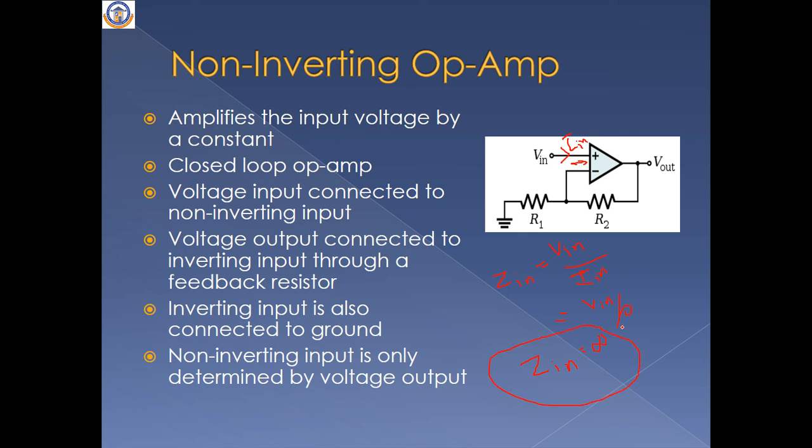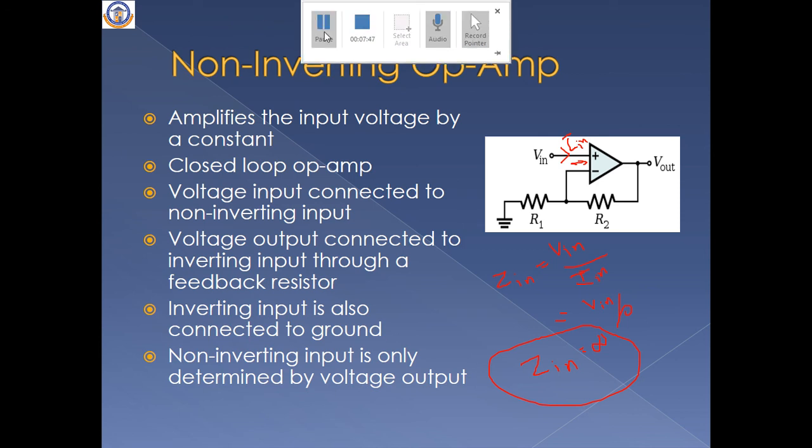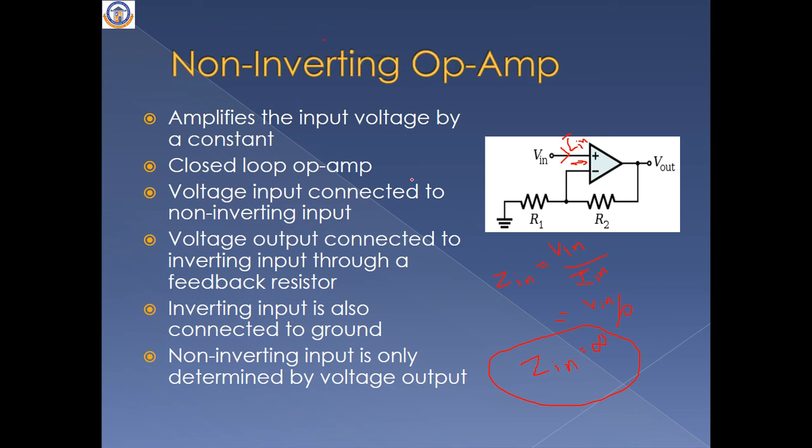So if any circuit has infinite input impedance, you can use that circuit at the output side of any circuit, and it will not be loaded.